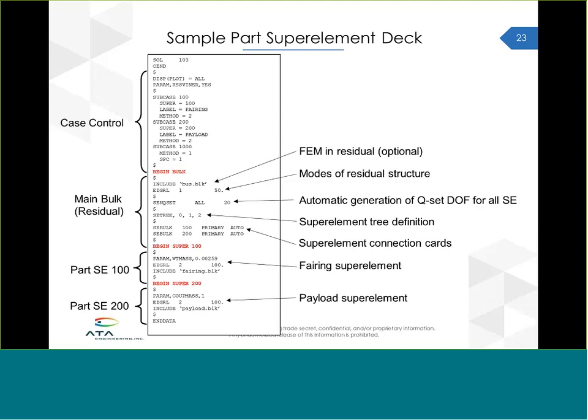This is completely okay to do in part superelements. Without part superelements, you would have to pick one or the other, and you'd have to probably modify one of your models or accept some inaccuracies in one of your models, because you can't use different parameters within the same model with other partitioning strategies.